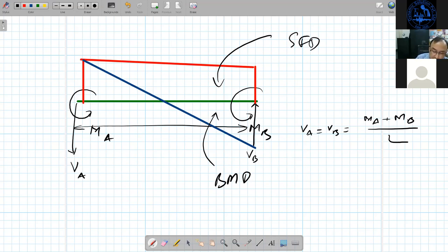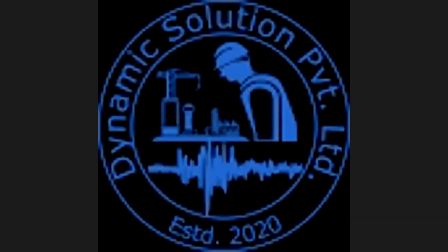Tarun Pandit has asked, with the increase in axial force, the ductility of the column will be less, and from PM interaction curve, with the increase of sectional dimension axial force will be more, so that for ductility purpose, it is advisable to use slender column rather than squat column, especially in bridge pier where axial force is very high.